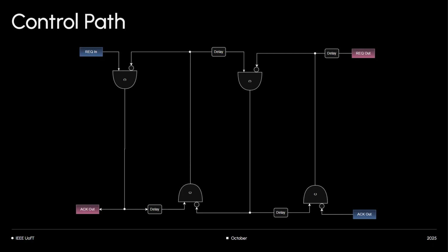The only difference from a synchronous signal is that there, activity happens only on the positive edge or the negative edge. In this case, you have activity happening on both edges. And these are localized: that stage's operation doesn't affect this stage's operation. These signals are localized to each stage and not a global signal. Does that make sense? That is really the black magic we're doing.